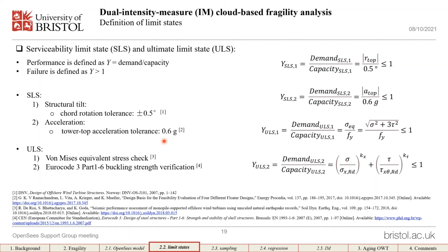But that doesn't have shear and torsion included within it. Oh, the torsion is elastic. It's a single value of elastic torsion defined for the cross section. And even for shear, it's a straight line, linear. And is that an acceptable assumption within the load ranges you are working with?